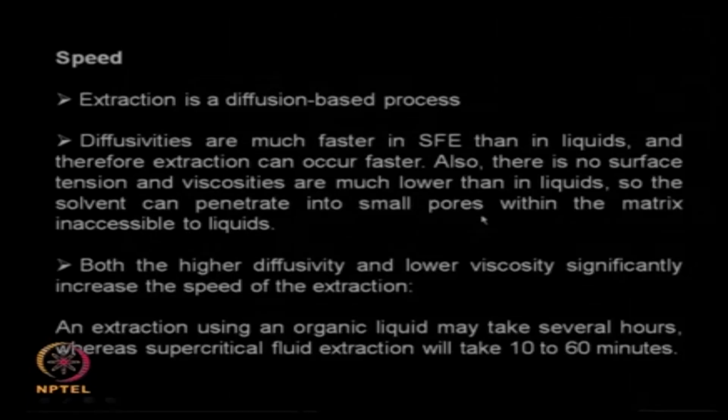So, it can enter very small pores, it can enter matrices which are inaccessible by liquids. So, the speed of extraction is also very fast. If an organic liquid takes several hours to complete the extraction, with a supercritical fluid I can do it in 10 to 60 minutes. So, we are talking in terms of an improvement in speed by a factor of 3 or 4.